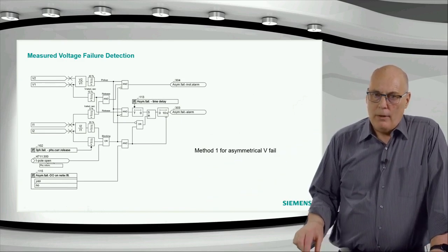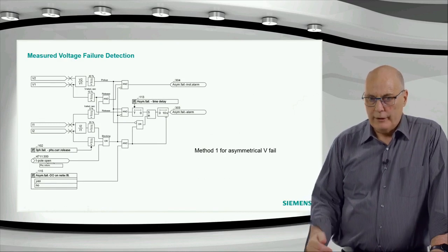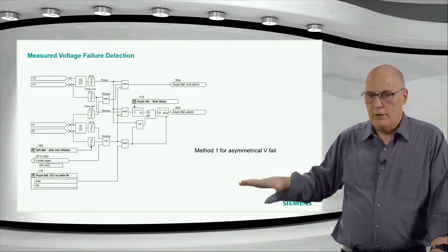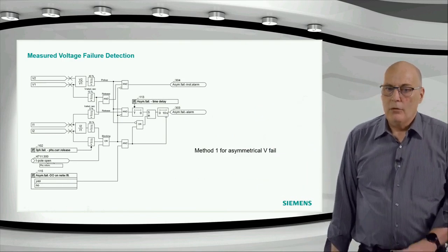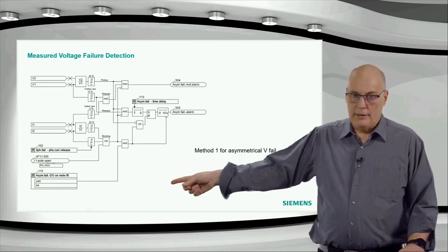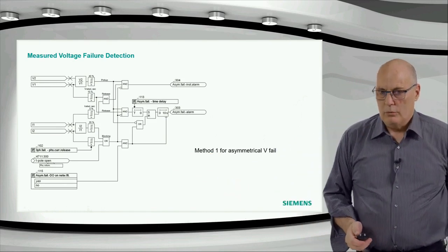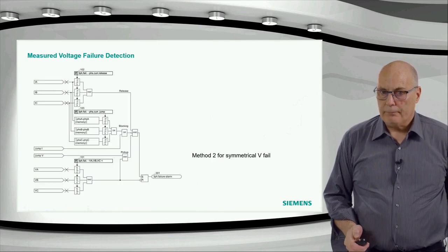Asymmetrical fail dropout on network fault, and you say set it to yes. Then, as soon as there's negative sequence current, it will always reset the fuse failure. Not what I would recommend. The recommended setting is no, but that is something the application person must check.